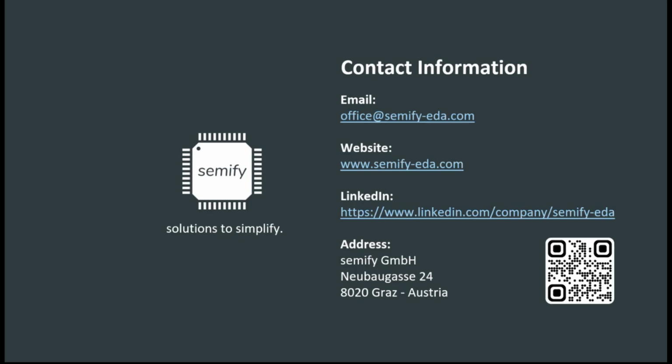The other one was a comparison with SystemC, because obviously a lot of people use SystemC as a verification environment, which is a lot more software oriented than some of the VHDL and SystemVerilog environments. Philip is saying SystemC is much more suited to high level modeling and high level synthesis, whereas Cocotb is much more suited to a test bench style environment.